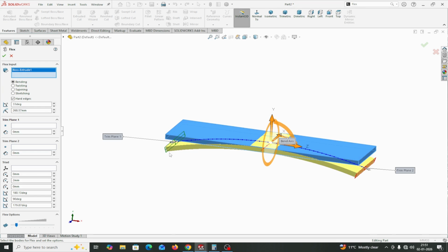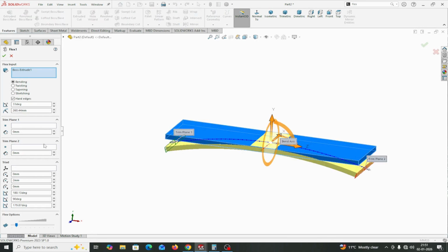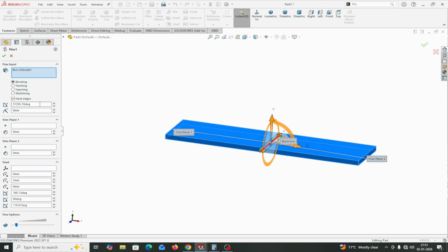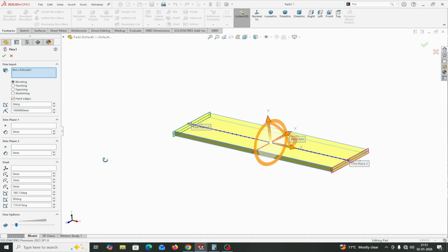bending will take place where our planes are located. I am not changing any plane direction or distance. If I hit the right button, the bending takes place. Again, edit, same thing. Suppose you put value 0 and 0 here also. This is the original position.